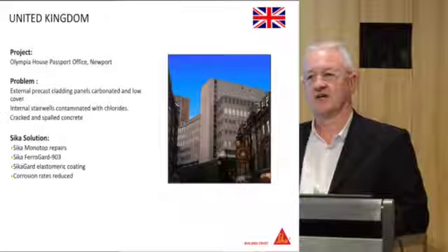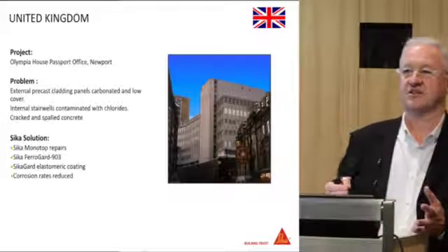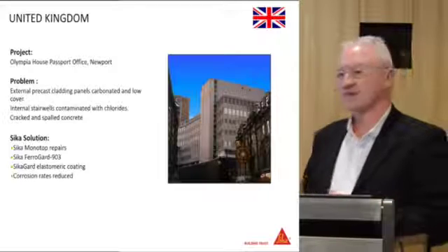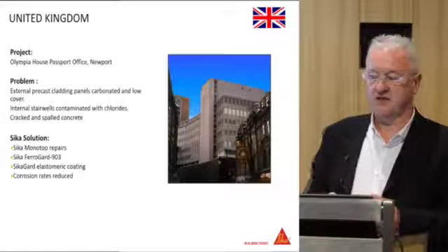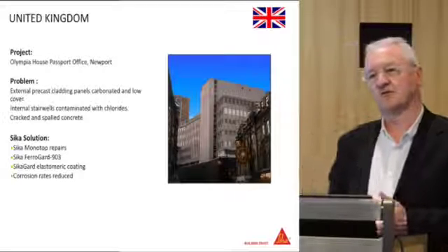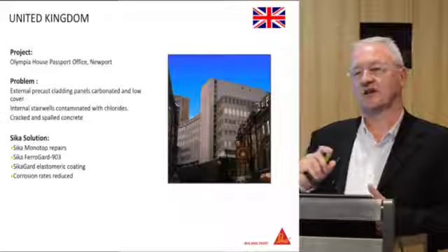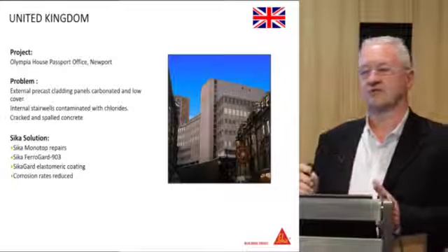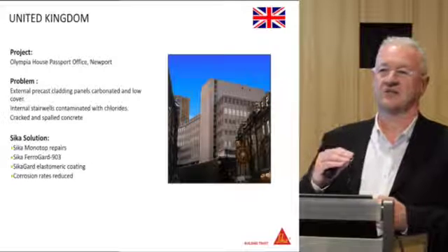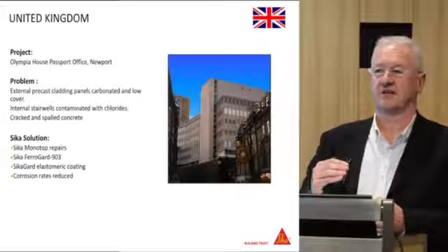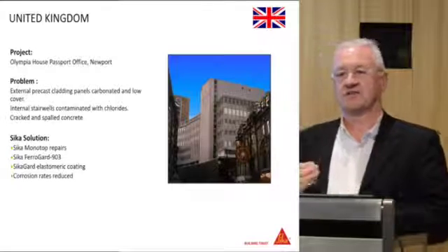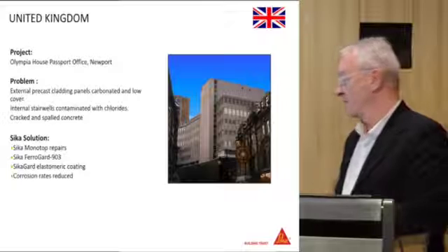that were being formed. Now, Chris mentioned using half cells, which really aren't appropriate for carbonated structures. Also, with half cells, when you look at BRE Digest 444, which clearly outlines quite a few of the electrochemical monitoring techniques, there are criteria there, and basically half cells is all based on probability. It may or may not happen, and it may happen over these years, but it's not really that conclusive.